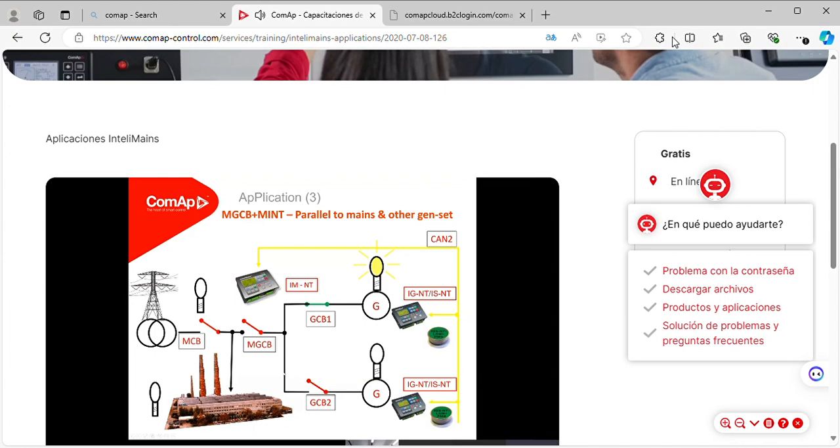The second genset would be started. So the second genset will try to synchronize with the first genset, and they are performing load sharing and var sharing between them. So everything is normal. Now automatically once both of these breakers are closed and this information is relayed back over the CAN bus to the InteliMain controller, it acknowledges both gensets being running and both the circuit breakers being closed.